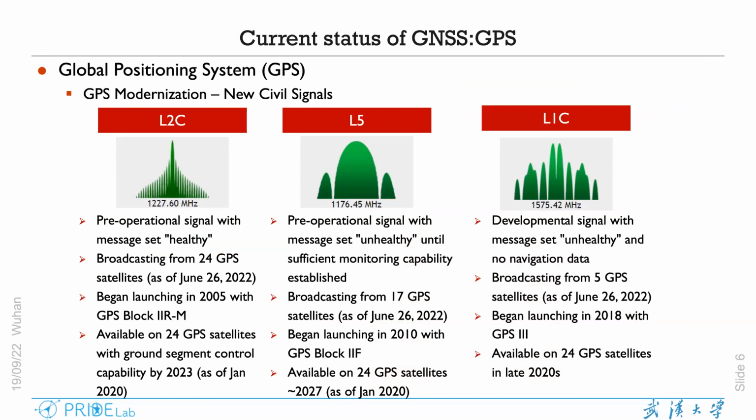They use some advanced coding technology to have more pseudo-range measurements retrieved from the carrier phase data. Here we can use the L2C to recover the L2 signals to have more robustness for the carrier phase tracking, and L5 signals are developed to improve the positioning efficiency.